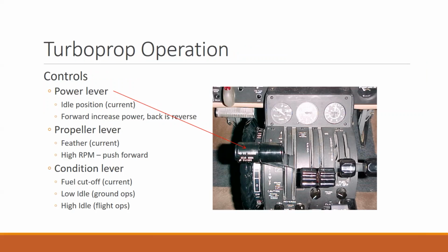Okay, behind that gate. The other style I've seen is instead of physically lifting up on the knobs, there's some kind of a trigger that you grab with your pointer fingers or your middle fingers underneath the knobs. So you have to lift that trigger up and then pull back on them. Once they're behind that gate, though, you don't have to keep pulling the trigger. Then you can just operate them like normal. And when you bring them back forward, as you come in front of the idle mark, they will either snap back down so that you can't accidentally pull them back again, or the trigger will release. You'd have to pull the trigger again to bring them back.